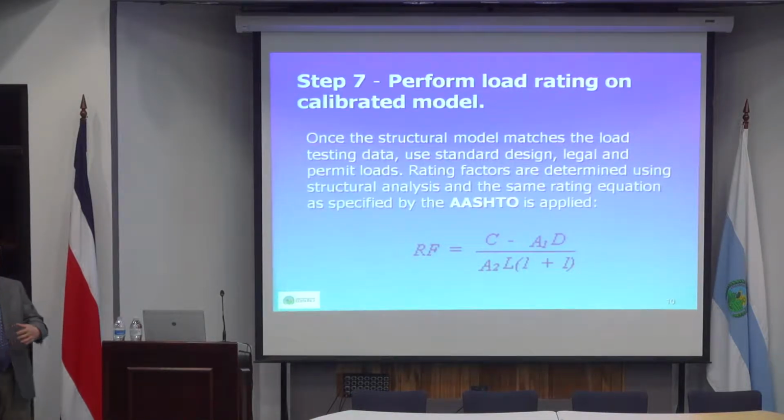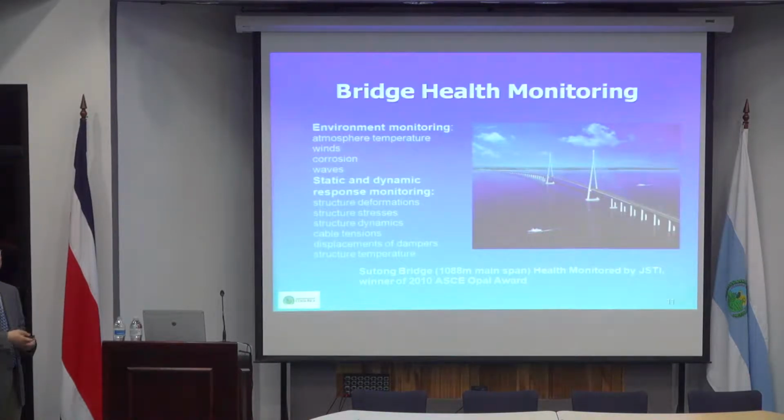bridge and truck vibrations. Then you can actually put in a reduction sign. For example, if it was a 100 kilometers per hour speed limit, you put in an 80 kilometers per hour speed limit. So when you do a load test at 80, you get a much smaller impact. Then you can use the smaller impact and that will work. So all you need to do is put the speed restrictions on the bridge. Okay, so these are two very much independent components.